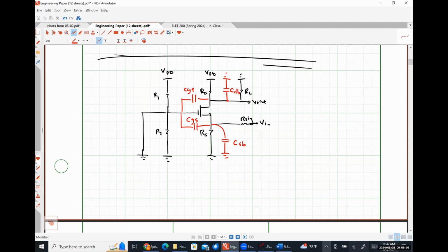So you will actually need to look for the resistance, which to me looks like it's going to be RF in parallel with RSig in parallel with whatever we see looking up into the source terminal, which I think would be one over gm in parallel, or not, but I'm not 100% sure on it. Something akin to that. Nothing wildly gross.